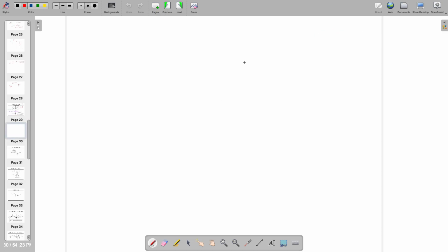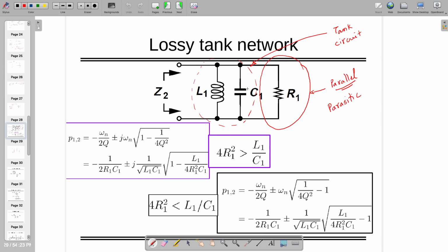Both are kind of tank, L and C. One is keeping current and one is keeping voltage, right? And they are exchanging with each other when you are giving the input. That's why in general all people call this circuit a tank circuit. If it is an ideal tank circuit, you should not keep resistance. If it is a lossy tank circuit, then you have to add one extra parasitic, and when you add that altogether, you will get some extra equation where you will have some real part also.